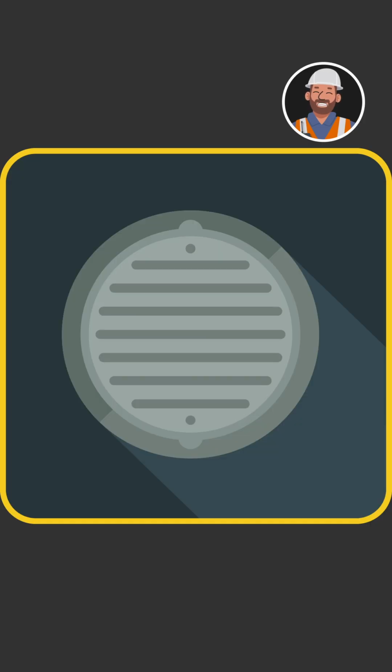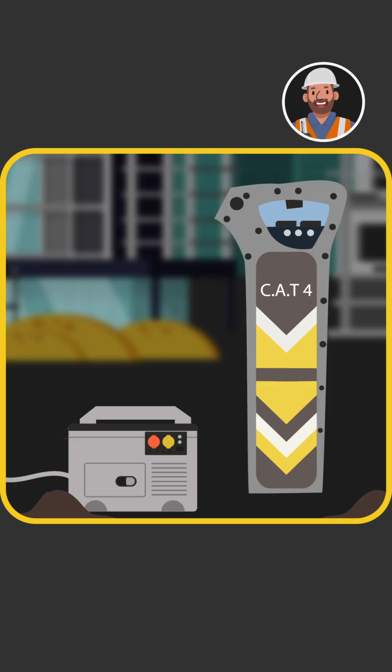Visual inspection on site. Spend time identifying clues of buried services. Look beyond the immediate dig area for manhole covers, gully gratings, reinstated trenches or road scars, marker posts, telecom boxes and valve covers. Cable detection. Use a cable avoidance tool, CAT scanner, and signal generator to locate buried services before and during the excavation process.